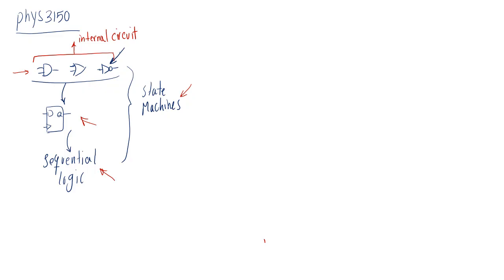In our designs, we're going to be using two different kinds of transistors, and we use transistors as switches in this course. So we're going to use MOSFET transistors. MOSFET stands for metal oxide semiconductor field effect transistor. We're going to use N-type MOS, or sometimes we call it NMOS, most of the time actually, or P-type MOS, or PMOS.